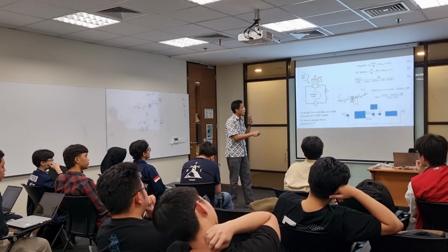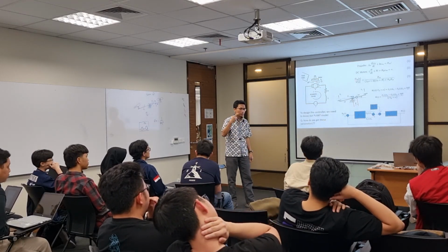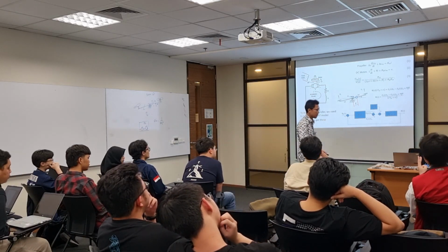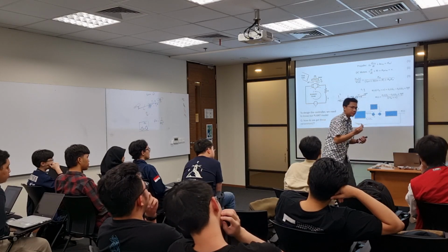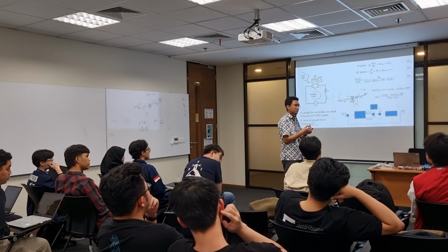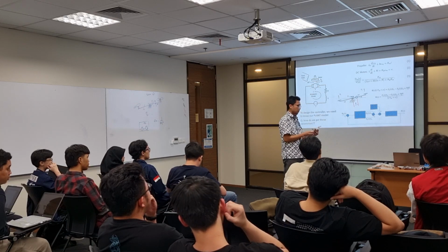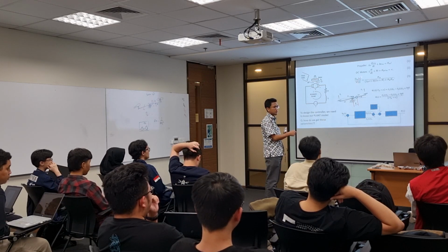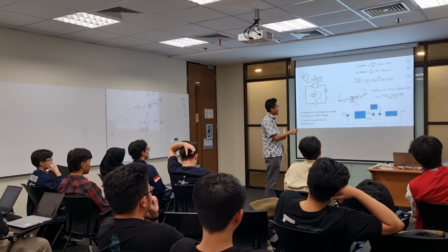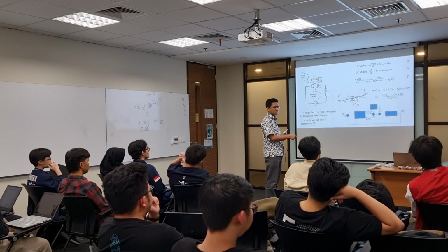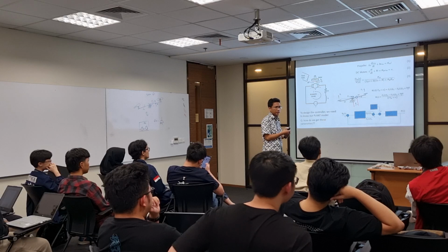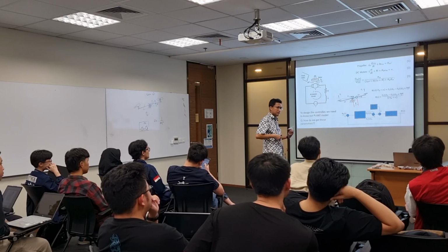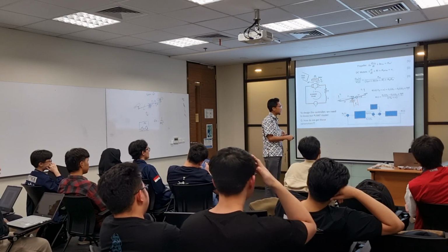Omega here is the rotational speed of the motor. So ideally you have two transfer functions. You can view it as two, which is from the voltage to the omega, but then from the omega to the thrust, you can relate them also. So the input coming to the system is the voltage, and the signal you give into the system is the thrust.